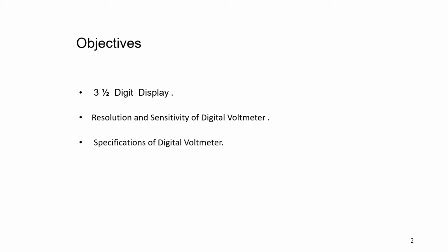So when the control register is an 8-bit register, its reading would be 1 followed by 7 zeros. This initial setting of the register causes the output of the D to A converter to be half of the reference voltage, that is half V. This converter output is compared to the unknown input by the comparator.